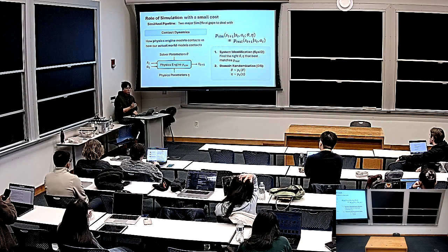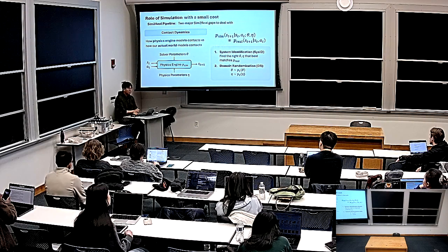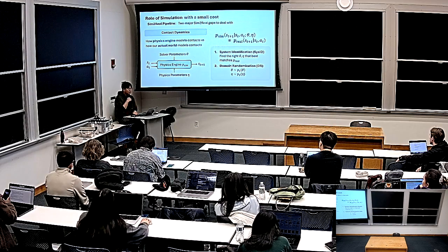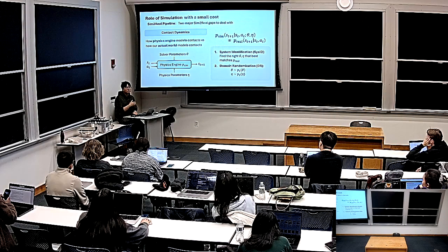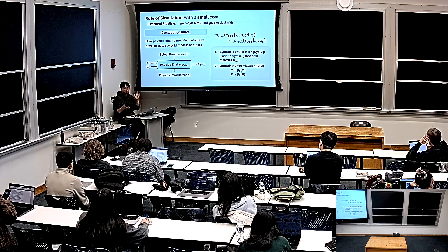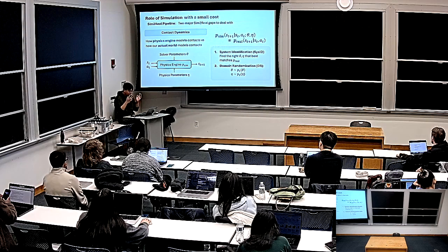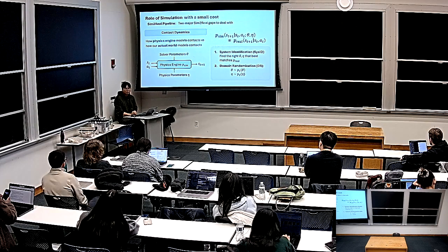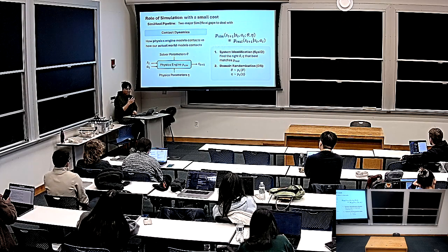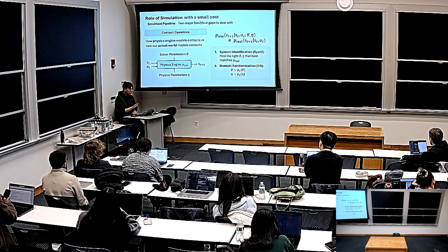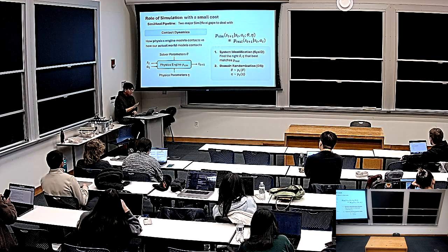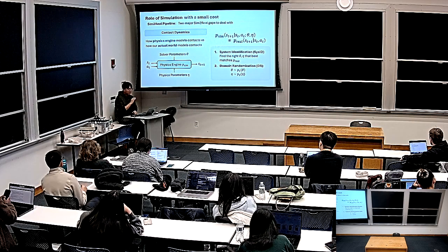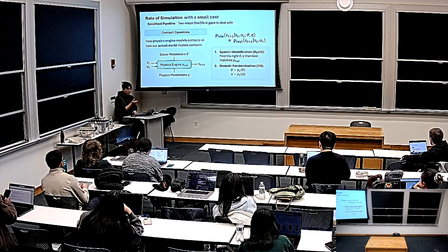So in those scenarios, what we do is make the simulation engine randomly sample these parameters from a fixed range, so the policy can be learned to robustly act and behave in a reasonable range of these two parameters. So in general, system identification and domain randomization, as robotics practitioners, we like both in many scenarios.